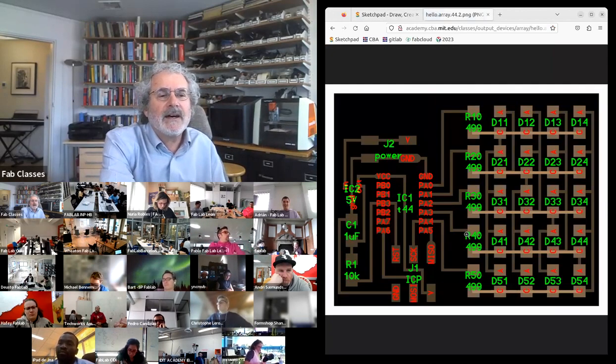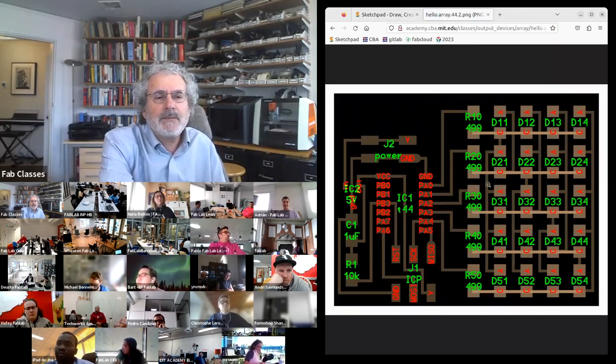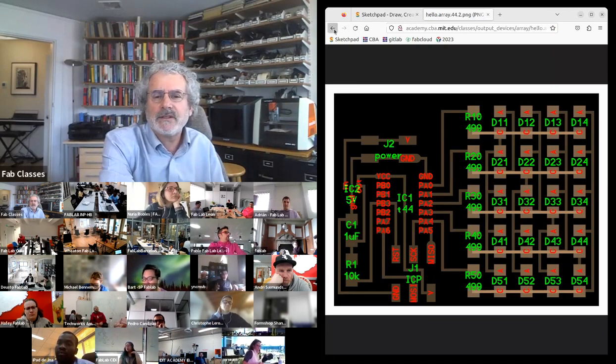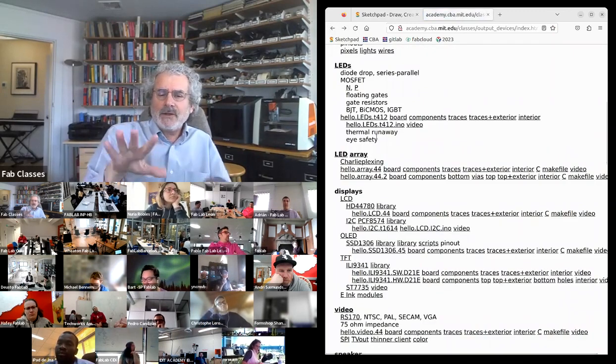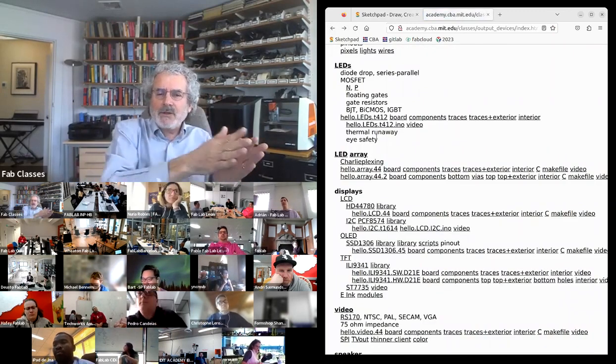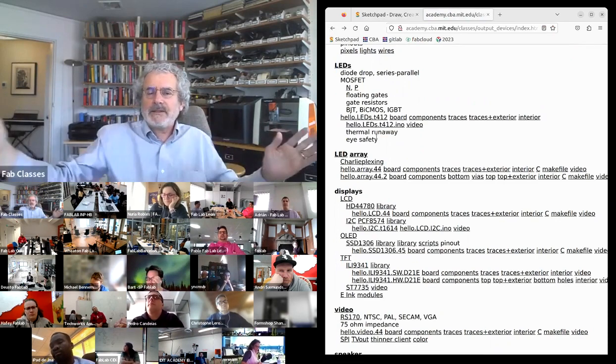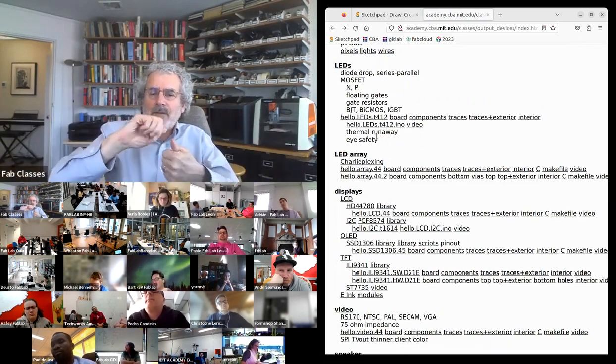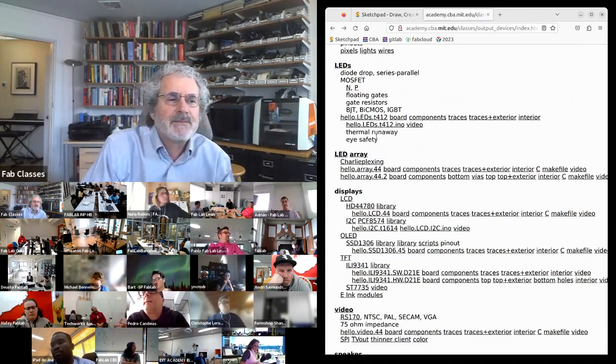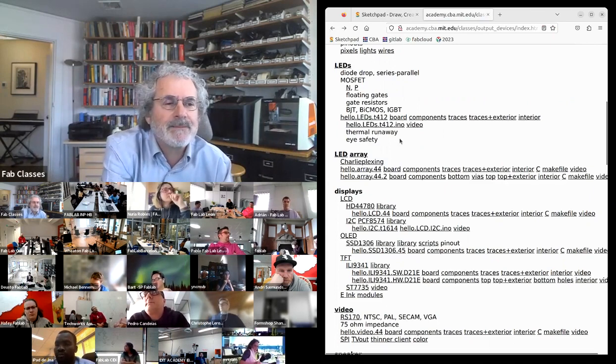In this case, I've got my pins, and each pin is going to rows and columns, and then I've got the current limiting resistor. And so you can use this to make square arrays. You can also use this to make linear arrays, but you can control the square of the number of pins. So that's Charlieplexing.